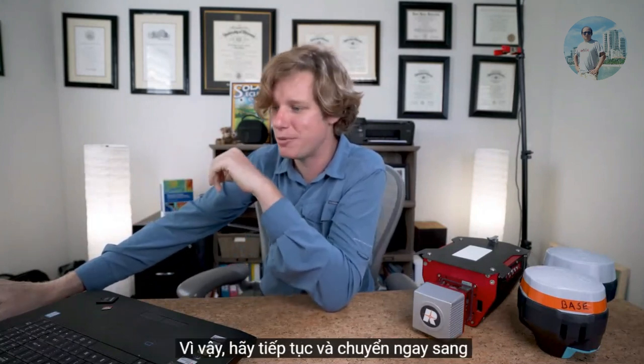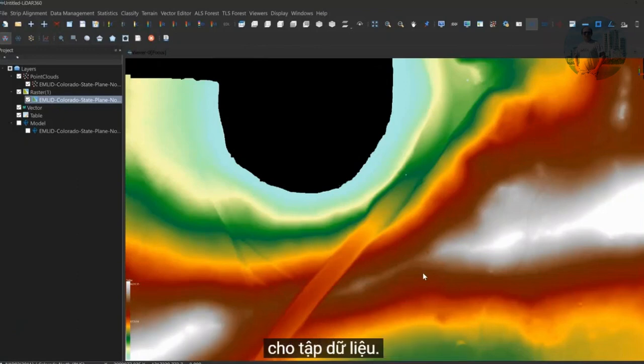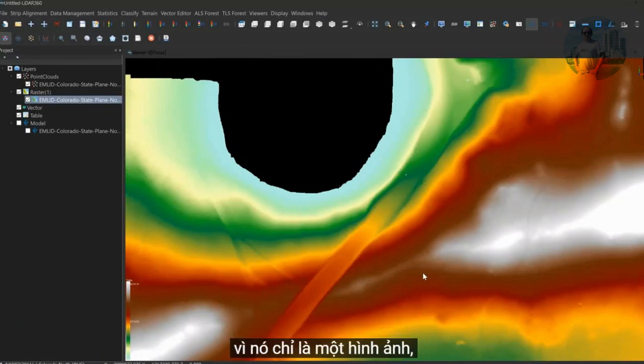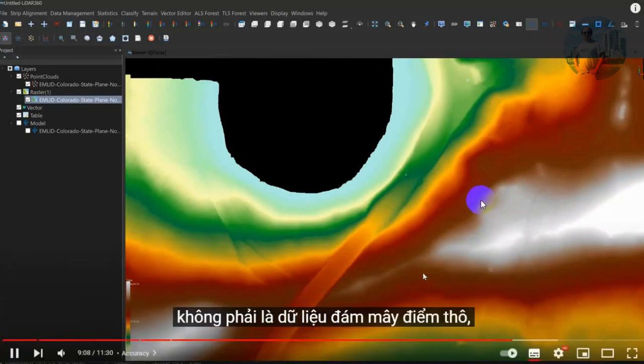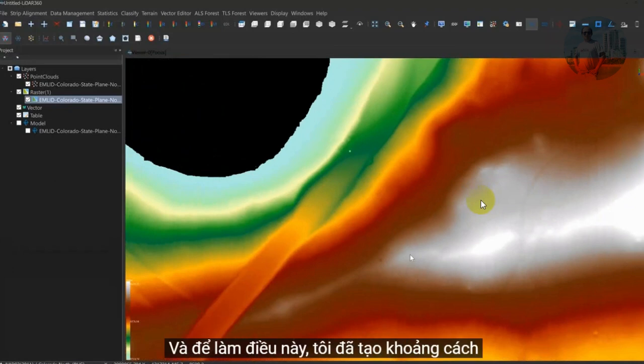So let's go ahead and just jump right into the digital elevation model for this data set. This is the digital elevation model for the data set. It has no trees, just the ground, and it's a TIFF representation of the LiDAR data. This is very easy to import into other software because it's only an image. It's not the raw point cloud data. It's just an image of the heights associated with the ground. And for this, I did a 1 foot spacing and interval for the DEM.